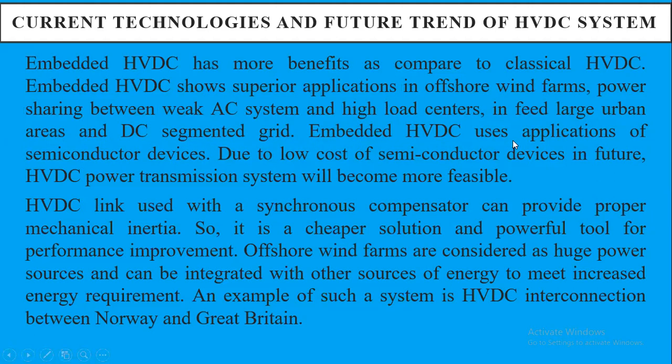Embedded HVDC uses applications of semiconductor devices. Due to low cost of semiconductor devices in future, HVDC power transmission system will become more feasible. HVDC link used with a synchronous compensator can provide proper mechanical inertia. So it is a cheaper solution and powerful tool for performance improvement.